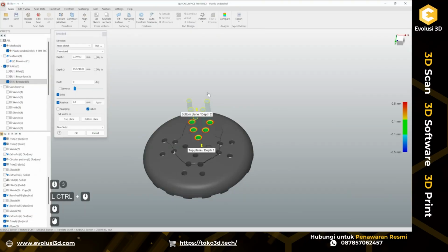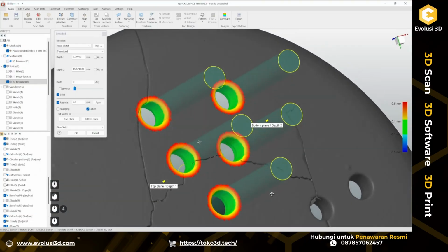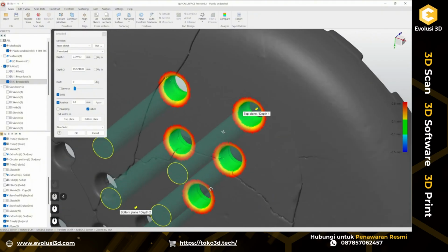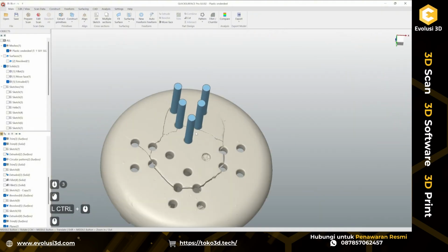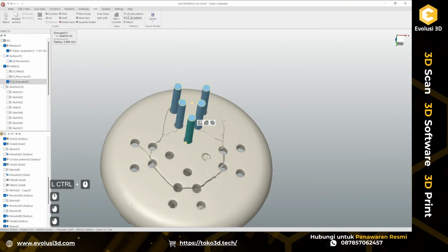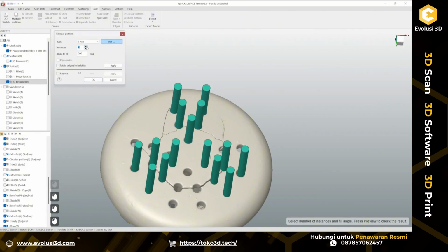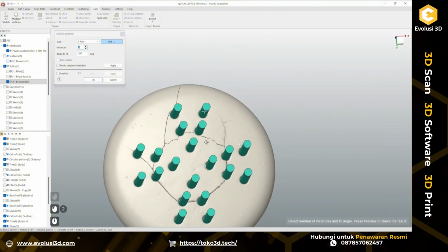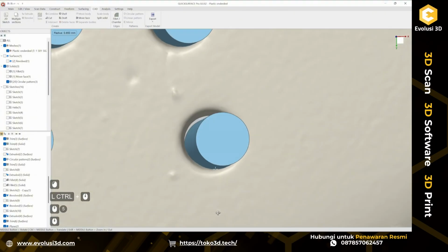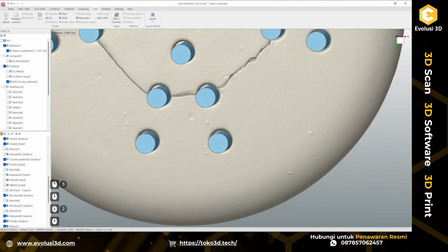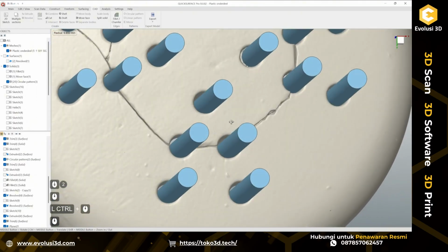So let's just extrude all of this. Okay, we can verify fitment. It looks good. And let's just create CAD circular pattern for instances, except, and of course, as we can see here by patterning again, it's getting slightly moved away somewhere.